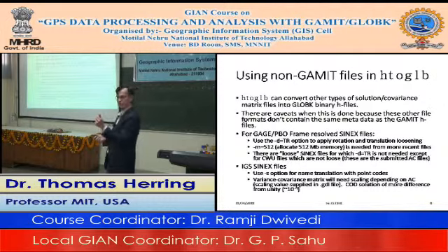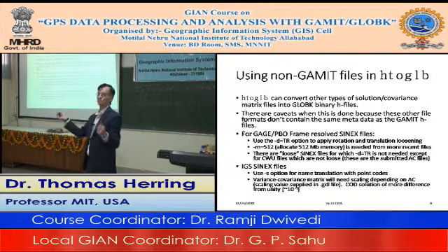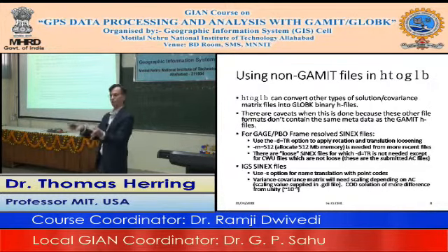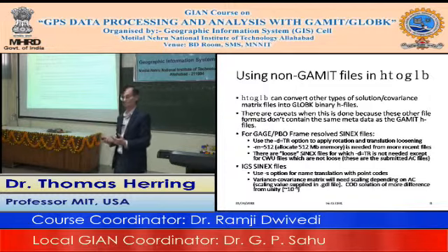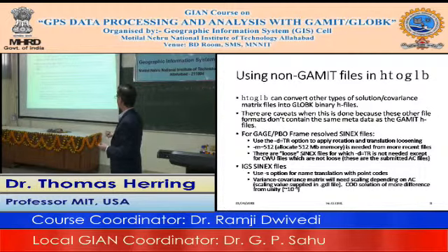H2Global does dynamic memory allocation, but it doesn't know before it starts how much memory it's ultimately going to need. It has a default value it uses, but sometimes it will run out of memory, and it will tell you fairly rapidly. So there's a -m option that allows you to set the amount of memory you want to allocate. For things like the PBO files, which have 2,000 or 3,000 stations, you need to allocate about half a gigabyte of memory to read those files in successfully. For the IGS SINEX files, you can also use the -s option, which does a name translation to make them consistent with the solution.